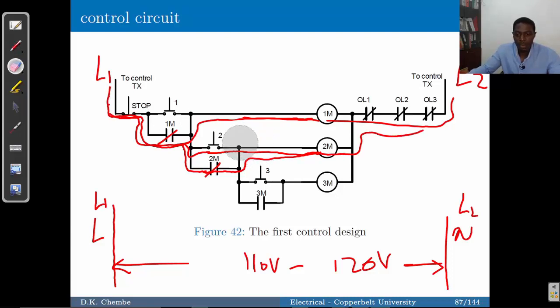So then what will happen now is that this will return to its normal status, and you have power flowing through this holding contact to M. And the same procedure now, push button number 3 has got access through this line and through this line. So power is able to flow up to here because this is open, and up to here because this is open. Once we push this button, current will flow and energize the coil for contactor number 3, which is going